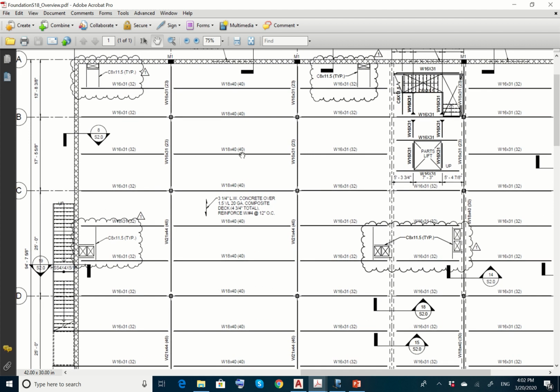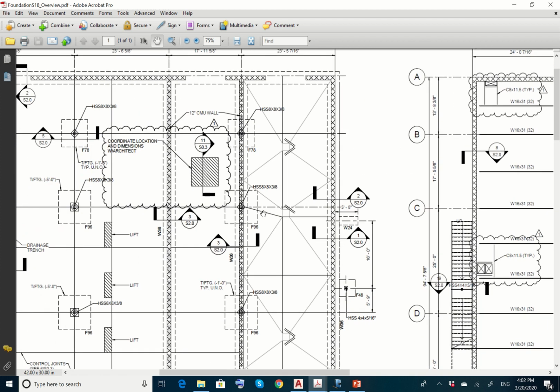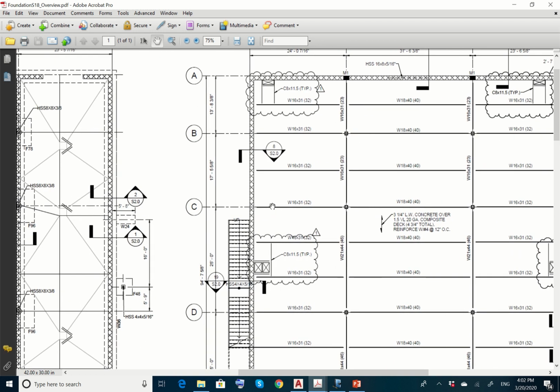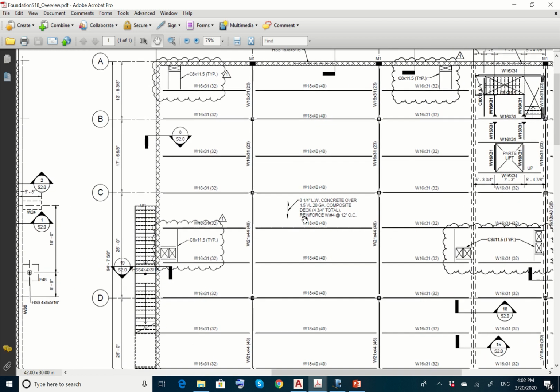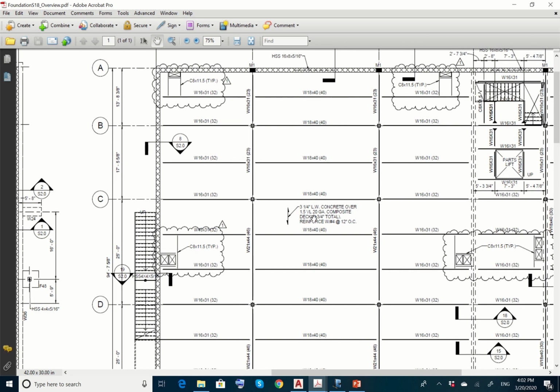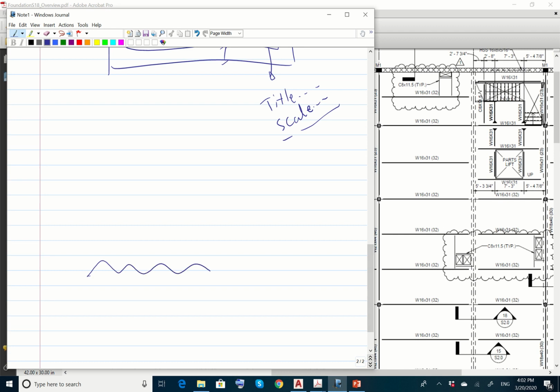And over here in the beams, you're going to draw the beams, and then the beams in the foundation, you're going to freeze, do a viewport freeze for the beams layer, okay? Over here, the floor itself is made out of a composite section. What's a composite section? A composite section is a section where you have some steel decking, and then on top of it, there is concrete, okay? Reinforced concrete.